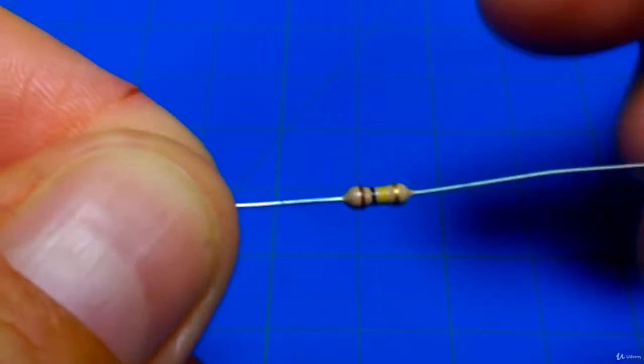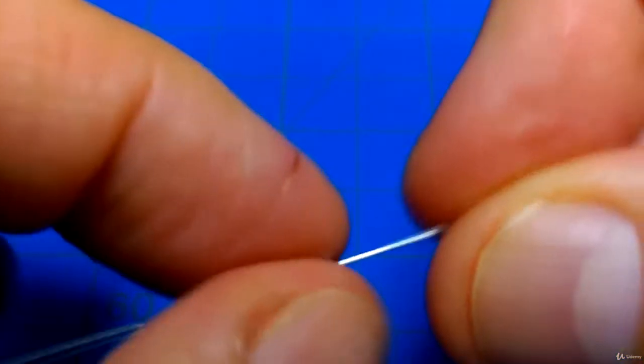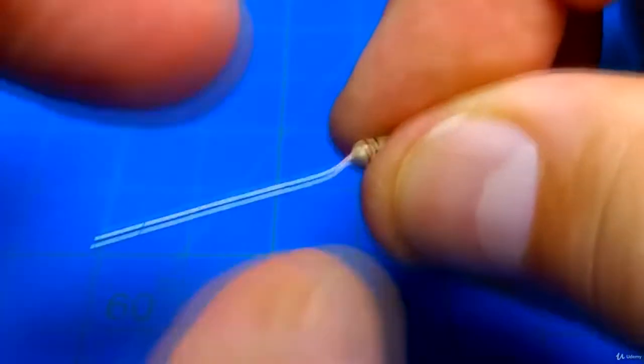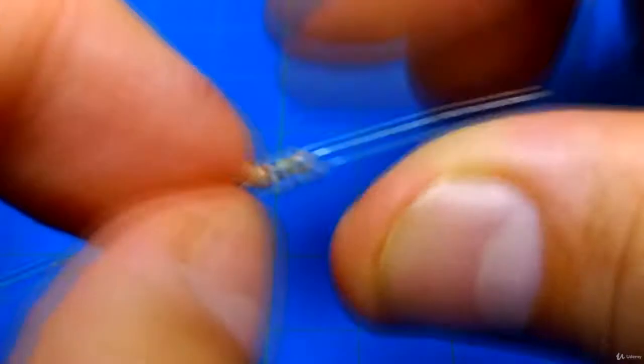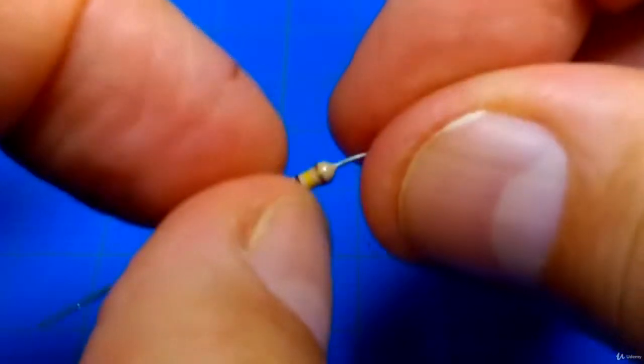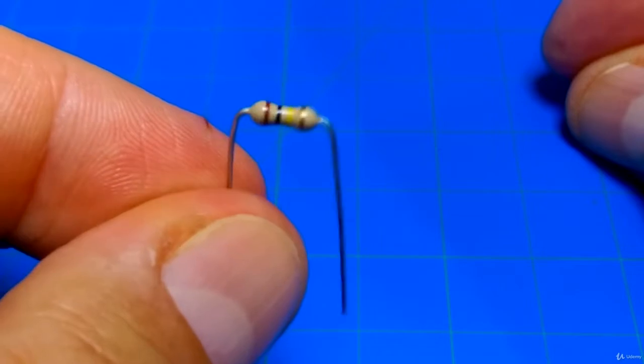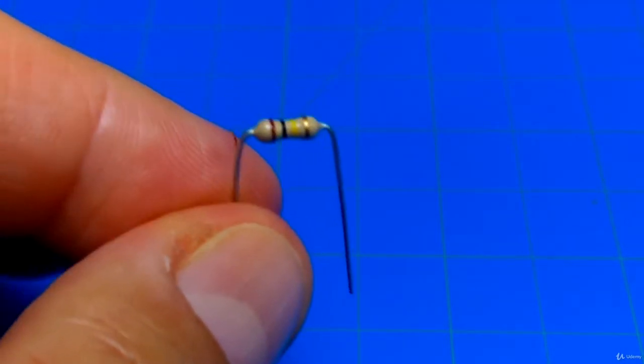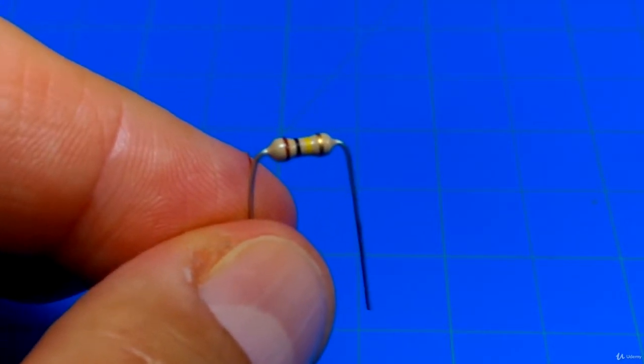Now, one thing is this resistor has leads, and you can bend them, right? You don't want to bend them too much. If you keep bending that back and forth, that will break. These have leads because this is called a through-hole component. The reason it's called through-hole is because you put it inside of a circuit board, a solderless breadboard or an actual circuit board, and put it through the holes.